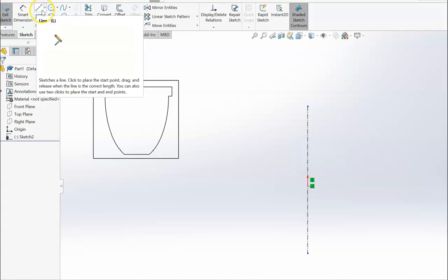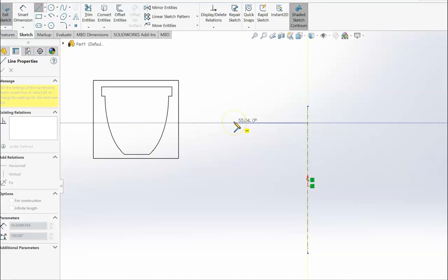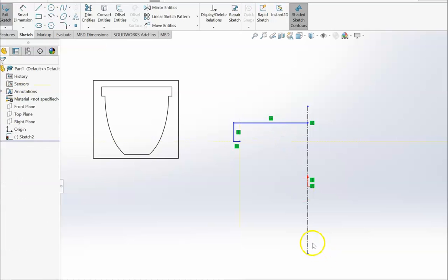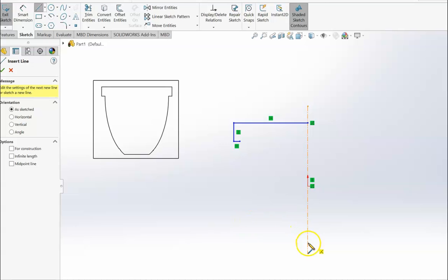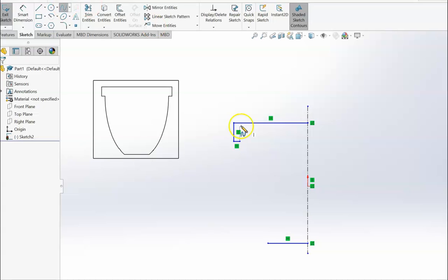And so similar to the other shape pot, we're going to start with a line. This isn't for construction, this is the actual shape. So we're going to go across to the left, make it horizontal, then down, vertical, across, horizontal, and I'm going to escape. I then want to draw a line that's horizontal along the bottom, like that. I'm going to click on the spline tool.